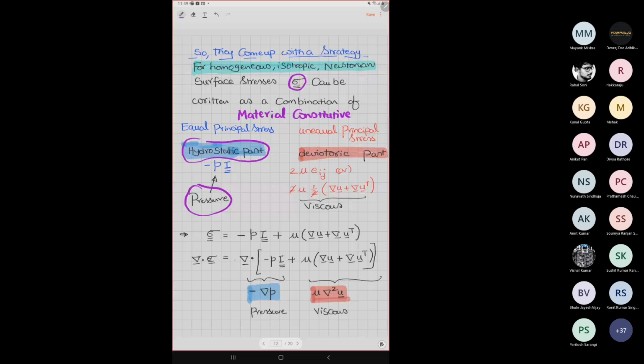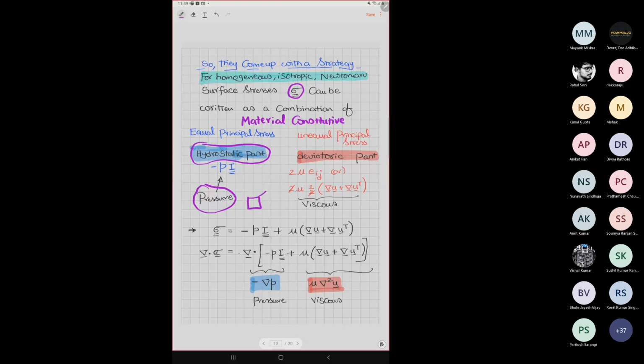You take a material, it might be experiencing complicated stress and strain, but equally normal to the surface, towards the surface, not away from the surface. Towards the surface, equally, can you really apply these kinds of components? If that is the case, you call that hydrostatic pressure. The stress component, if you want to write it, is minus P times the matrix 1 0 0, 0 1 0, 0 0 1.